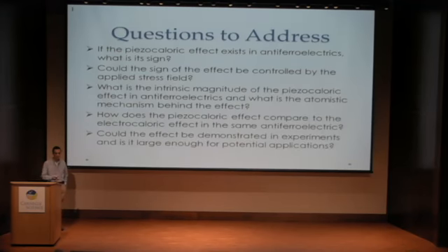So the piezocaloric effect is a particular caloric effect. Caloric effects can be defined as an adiabatic change in temperature and isothermal change in entropy upon the application of external fields, such as a stress field or an electric field. Now, in particular, the piezocaloric effect is associated with the reversible change in temperature upon the adiabatic application of the stress field.